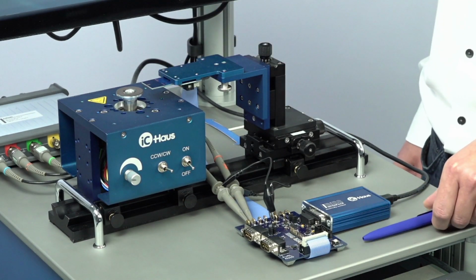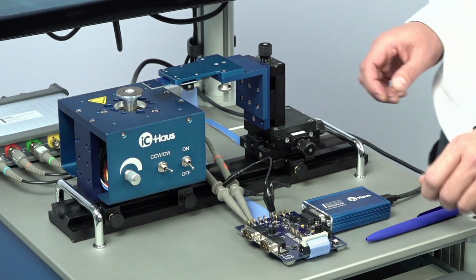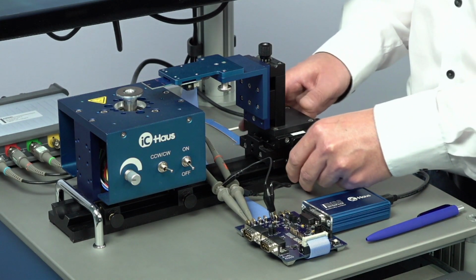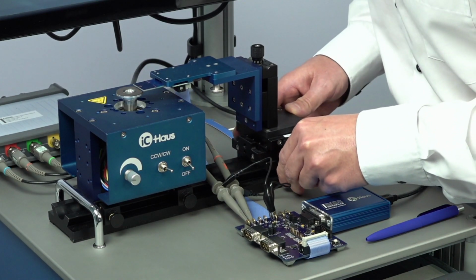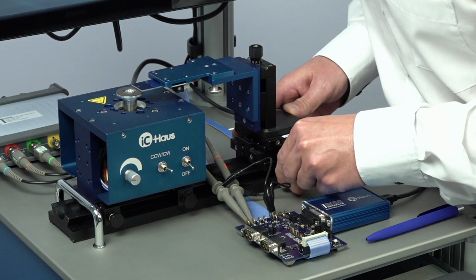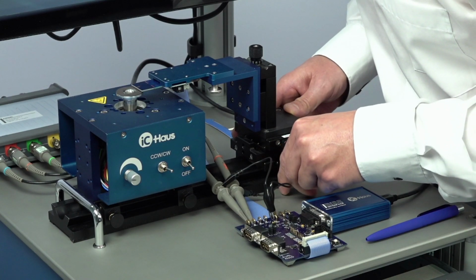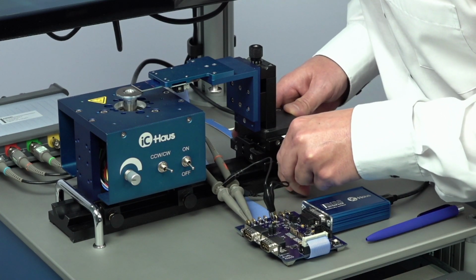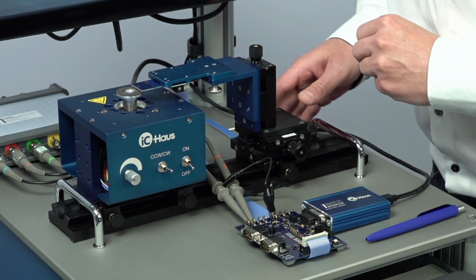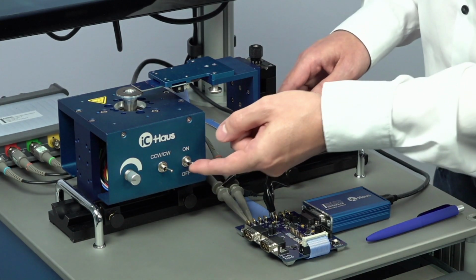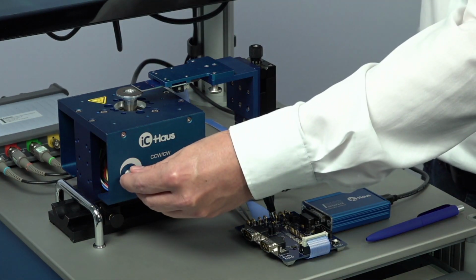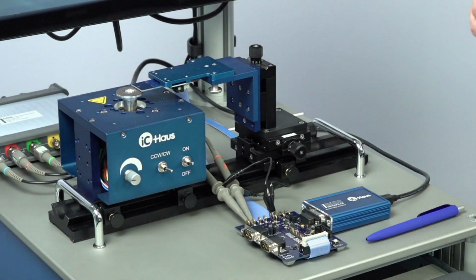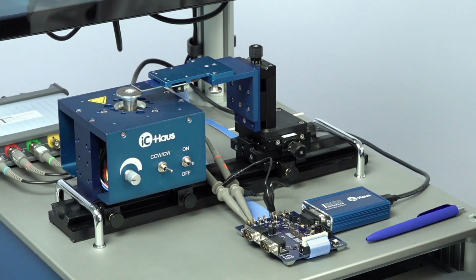Okay, to get started now, I would just like to position the iC-MU relative to the code disk, and I just do this by hand now. So I push this forward, and just by eye do a really rough adjustment now. I tighten the screw, and I think that's fine for now. And I start the motor so that the code disk is turning now. Okay. And now I would like to switch to our screen here, which shows the GUI software.